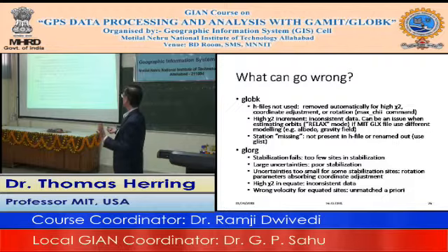The station is sort of completely missing. You think it should be there and you don't see it. Well, one thing it could be is that it might not have been present in the H file originally, and you just didn't realize that, or you may have renamed it out of existence accidentally. There's a program called GLList, where you can give it the GDL file and then an output list file, and you can also give it the earthquake files that you're using in GLOBK, and it will do all the renaming and tell you what you should expect in your final run.